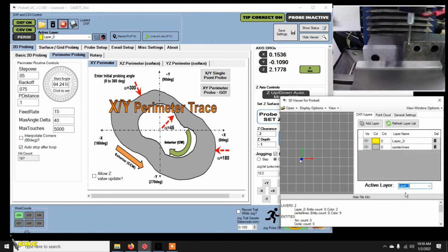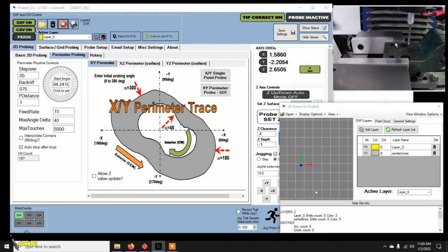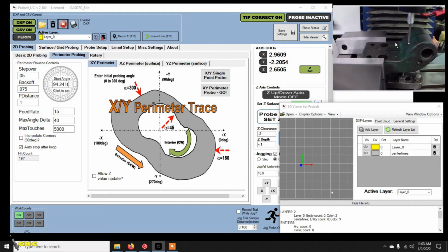And we'll reset up the part and probe it from the top. So we'll be back in just a second. Alright, we're back. I've reoriented the part into the vise upright. And so to finish off, we're going to have to reestablish a new origin for this file. Again, I'll probably choose this lower left-hand corner.